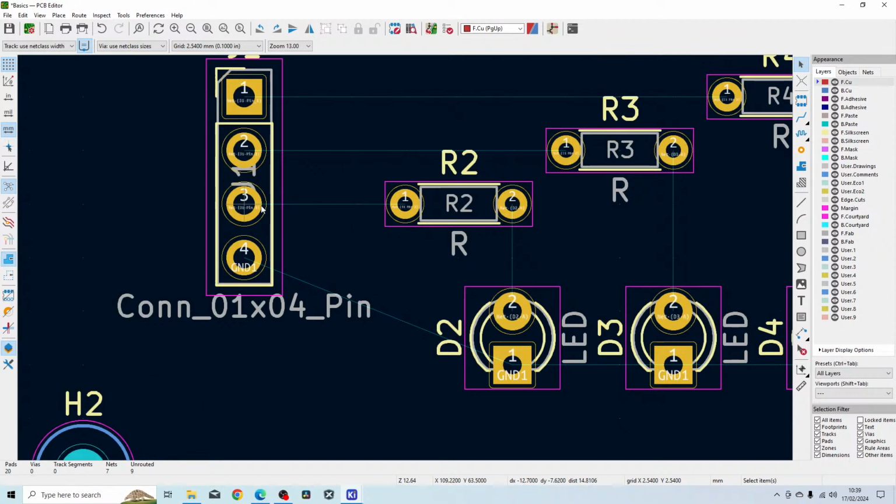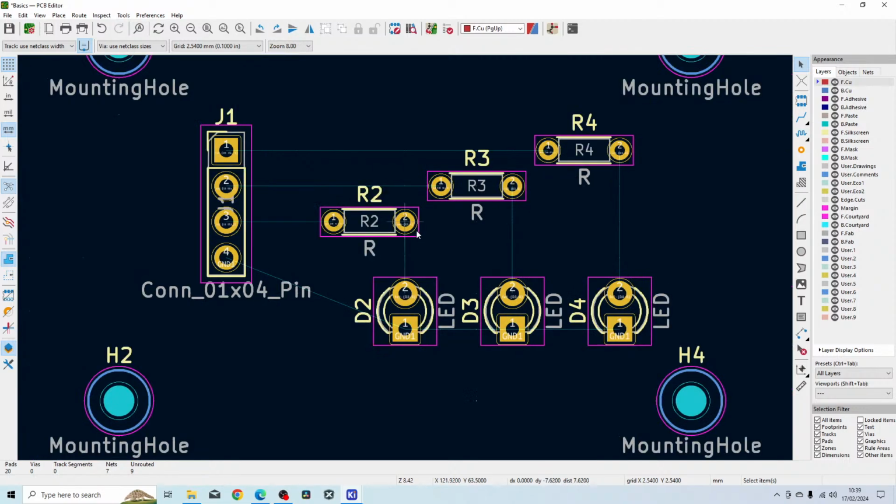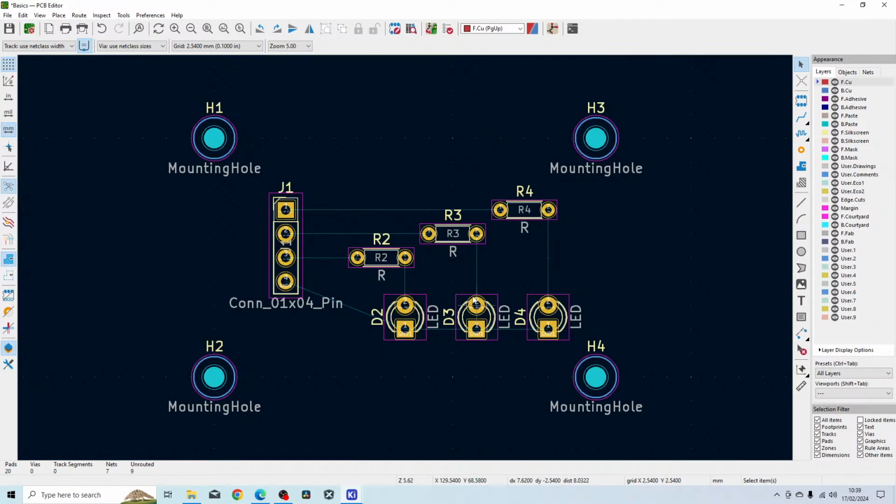But ideally what you want is the rat nest to be as least convoluted as possible, if that makes sense. Obviously, that means we can put our copper tracks down a lot easier. Component placement is one of the most important things you can do when you first start off the PCB design, because if you get the component placement wrong, putting the tracks down is going to be even more difficult.